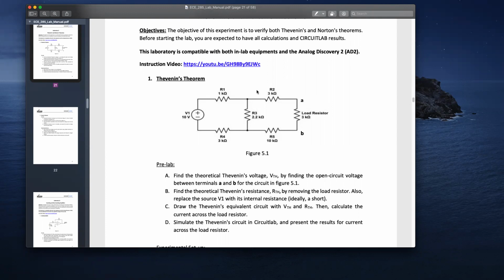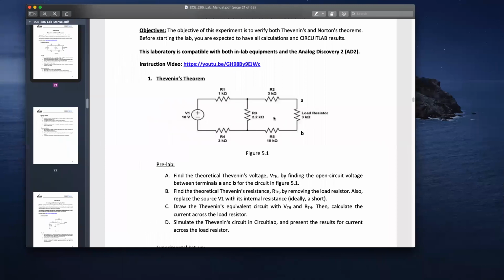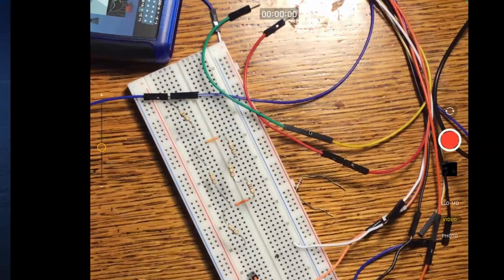Essentially, most of the voltage drop will occur across R3 and also around RL, because this is 100 ohms, that's 100 ohms, and that's 100 ohms. If you think about it, there's a lot of resistance right here and with this parallel branch. So most of the voltage being supplied should go across R3 and RL. Let's see if that's what happens.